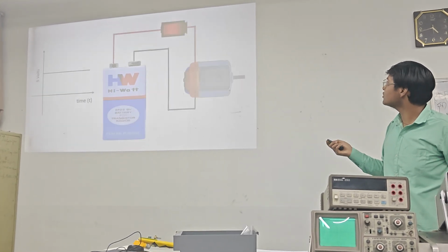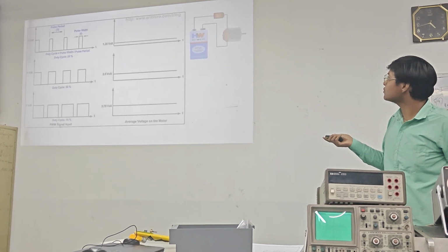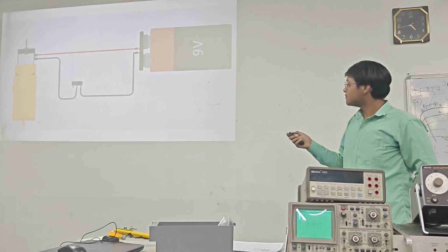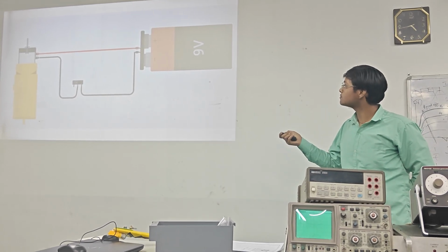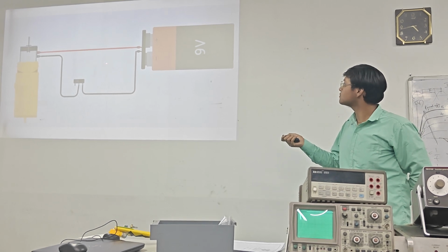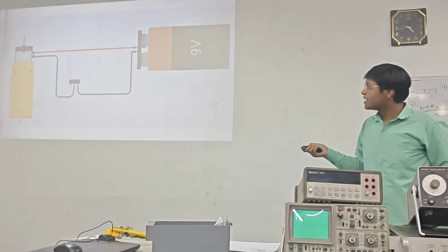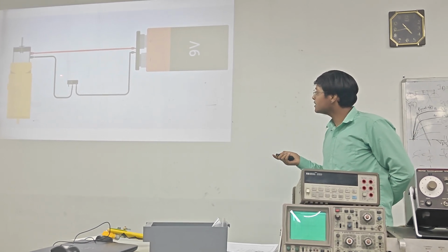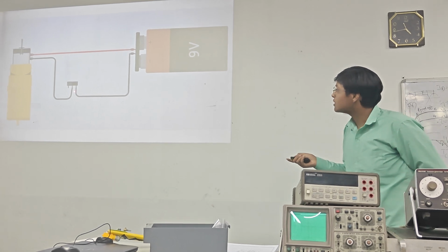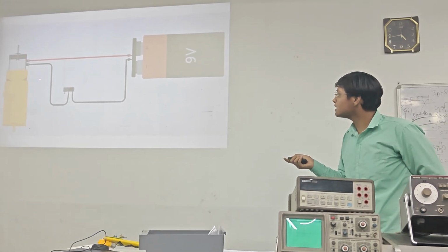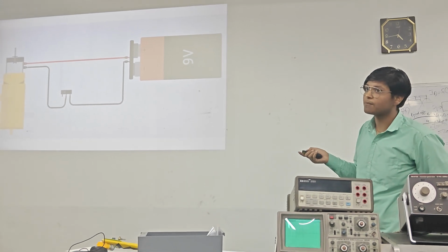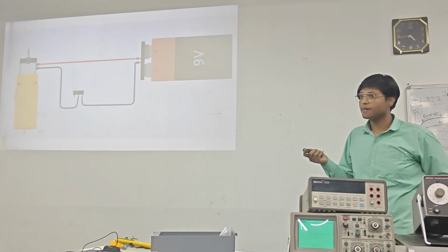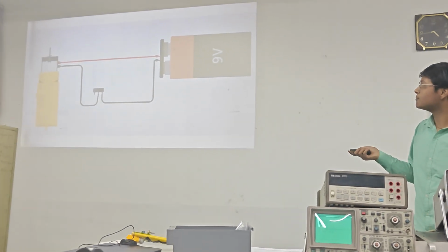So to overcome this problem, we have used a MOSFET as a switch. Here we simply connected our drain to the motor and gate to our battery supply, and the voltage modulation will be controlled from our 555 timer, which will be explained later.